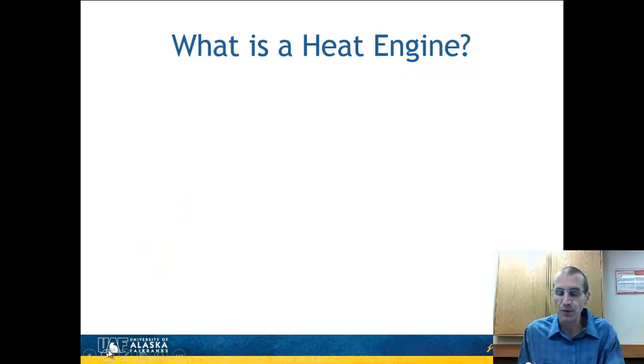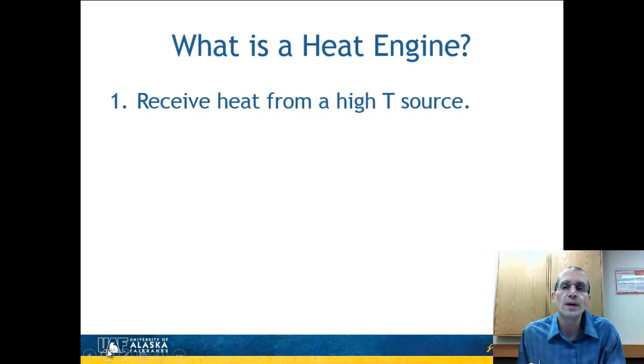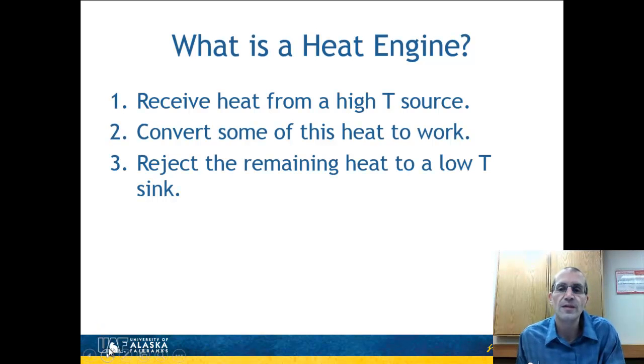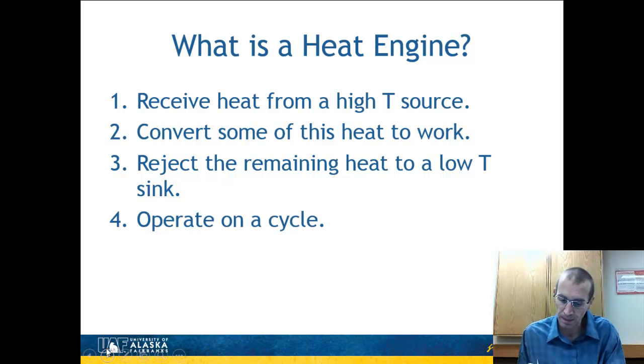So I'm going to give you four characteristics that characterize a heat engine. The first one is that this device will receive heat from a high temperature source. It will convert some of the heat that it receives into usable work. It is then going to reject the remaining heat to a low temperature sink. And the fourth characteristic is that it's going to operate on a cycle. If you have a device that meets all four of these characteristics, we would call that a heat engine.